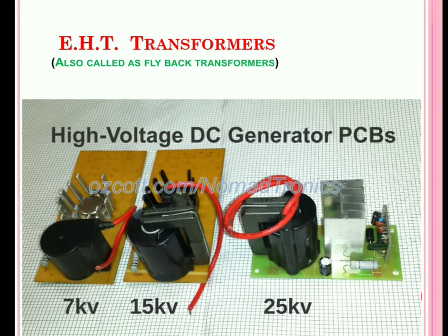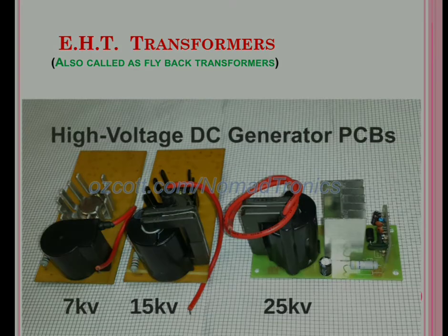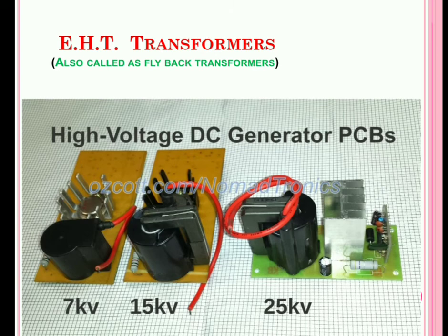During flyback it comes back very fast. Normally in televisions 52 microseconds is the writing scan side and 12 microseconds is the flyback time. During this flyback the beam is cut off to make it invisible on the raster.